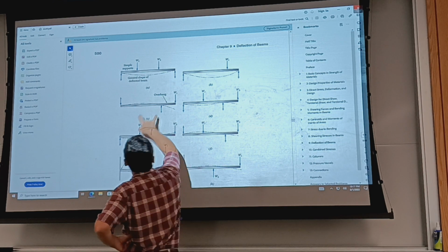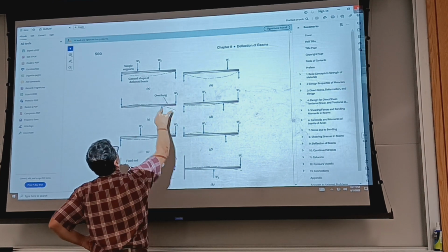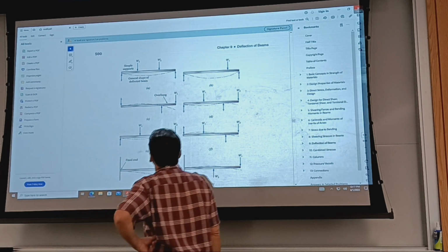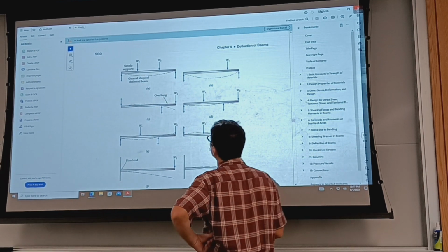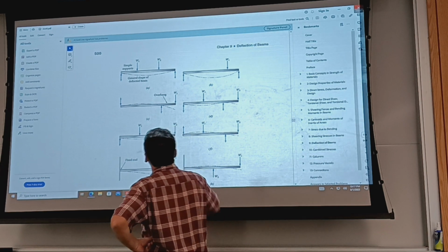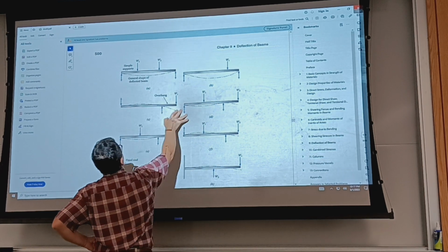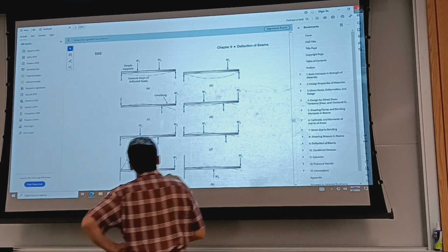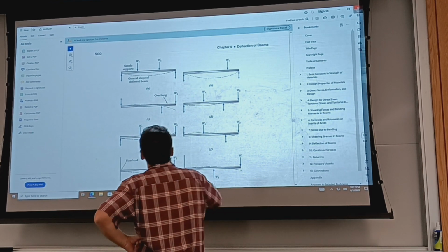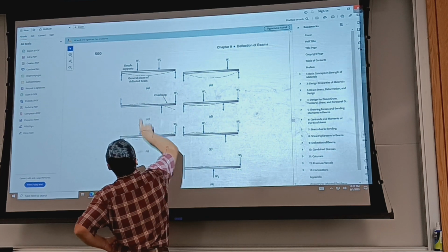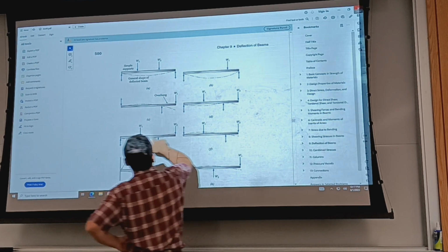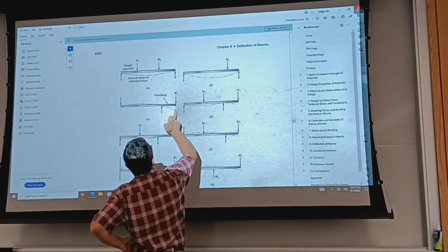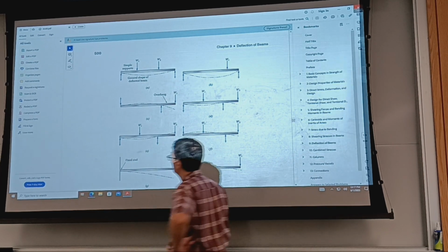And then if you have an overhang like you see here, so simply supported with an overhang, and you have the load, this would be the shape of the deflected beam. It's a smooth curve, and it depends on the load application, where the loads are positioned. Here I have the case from above where I added a load in between the supports, and you can see how, if this is big enough, it can reverse the trend of the free end and it will move up.